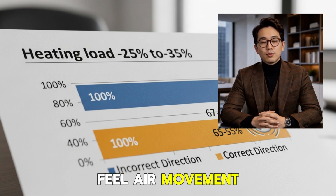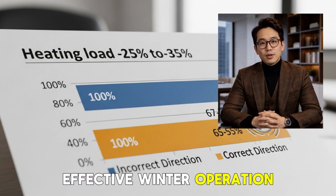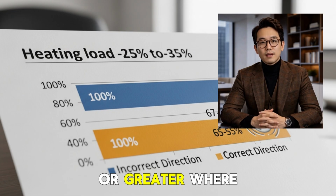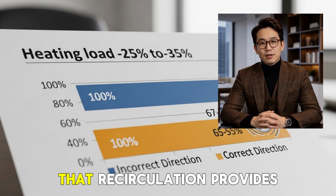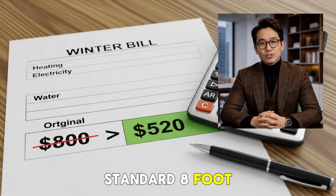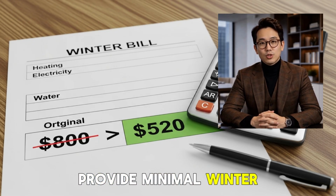If you still feel air movement, the fan may be too low or the room too small for effective winter operation. Most fans work best in rooms with ceiling heights of 9 feet or greater, where stratification is significant enough that recirculation provides measurable benefit. In rooms with standard 8-foot ceilings, stratification is less severe and ceiling fans provide minimal winter benefit.